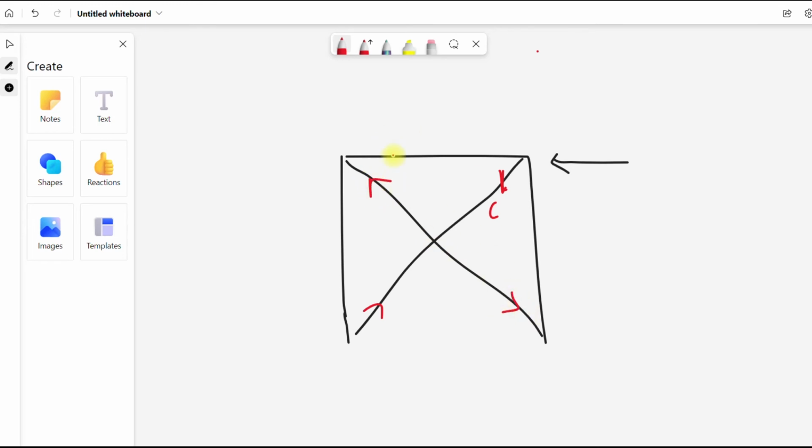And in bracing we don't use two different members, because let's say there's a wind load applied here, then in another load combination we have to apply it from the opposite end. So then there's a reversal of forces. This time this member will be in compression, this will be in tension. So when you're designing a bracing, you have to design for both tension and compression. So you have to see that the bracing member is able to take both compression and tension. So then I have to choose a section which carries both.